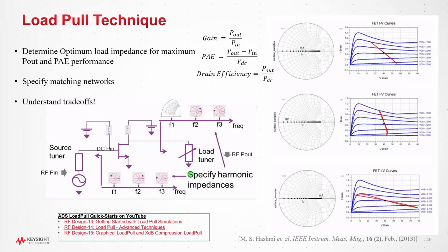And fourth, two more reasons. Fourth being you could basically do advanced topics. You could do a wideband input and see what the impact is on, like, the EVM through a load pulled device, like a power amplifier. And last but not least, there are ways in ADS to set up the optimization of a load pull device to make sure it converges under extreme conditions. If you want to know more about load pull, these are some great YouTube videos. Andy Howard and Anurag Bhargava are some of my colleagues that have done some excellent work there. I encourage you to check those out.